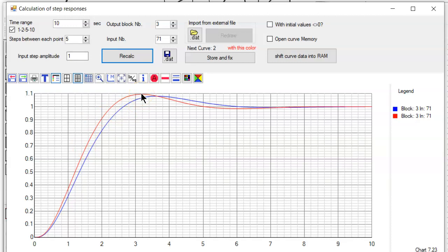If you say, okay, the overshoot is a little bit too high, then of course you can decrease the gain a little bit. Then you have a better overshoot. But I think you see here, this identification method is rather acceptable, rather good. Okay, so I can stop here and start with the next chapter.